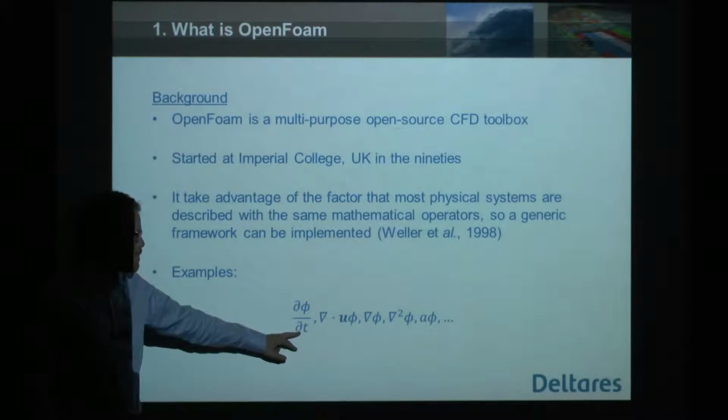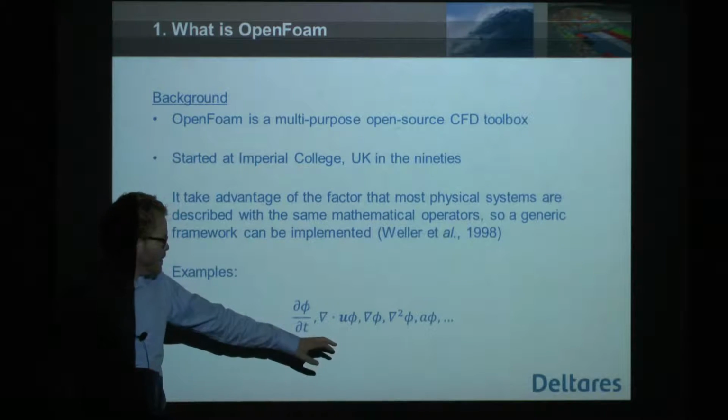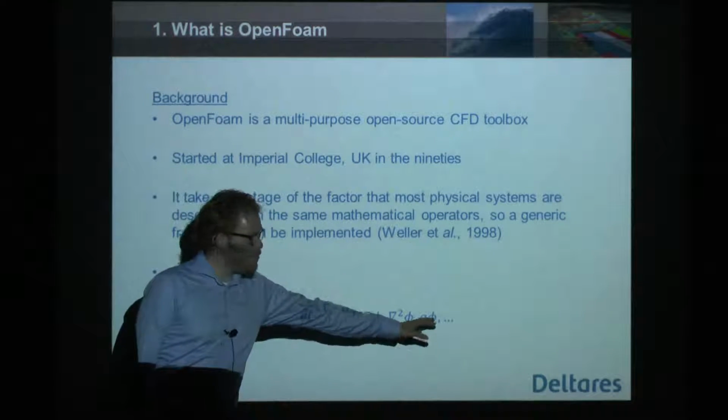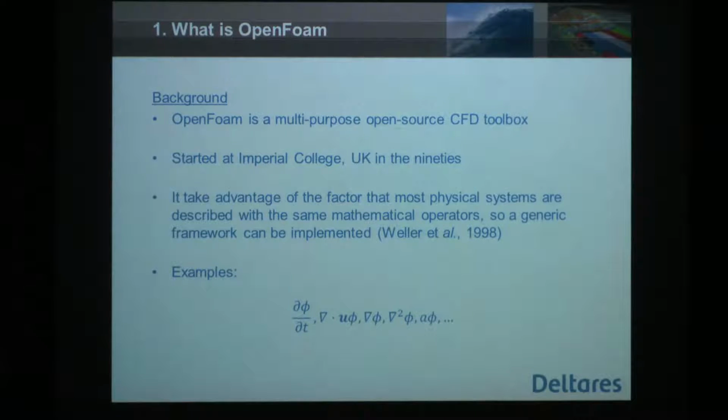There's something that changes in time. There's something that's being affected. There might be a gradient of the pressure field, for instance. There's some diffusion and some source terms. So if you don't assign specific properties to this phi, essentially you just have a generic toolbox for describing fluid motion. Could be turbulence properties, suspended sediment transport, advection diffusion of different species, or whatever you now want to be studying. So essentially you have a package that allows you to build your specific tools for what you study.